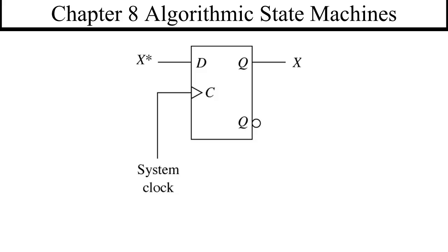The second point to make is that async does exist. If you think of a circuit in the middle, synchronous, it's dealing with the asynchronous world outside. It's dealing with input that's asynchronous, and it's dealing with output that has to be coordinated in an asynchronous world. So you're still going to have to deal with asynchronous signals at the peripheries of your system. Your goal is to coordinate turning the motor on, looking at the encoder, stopping the motor at the right spot.